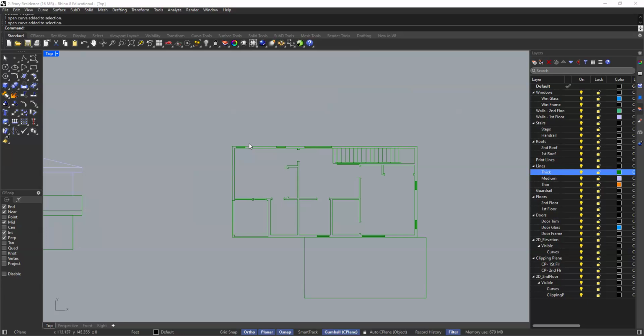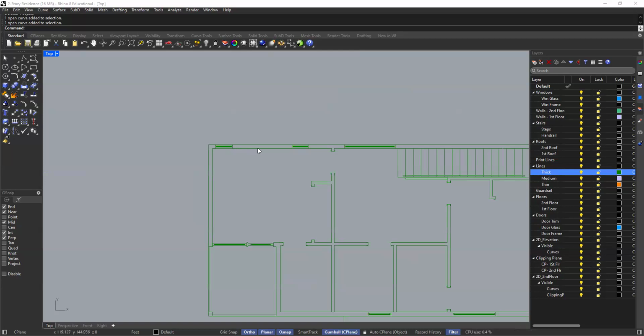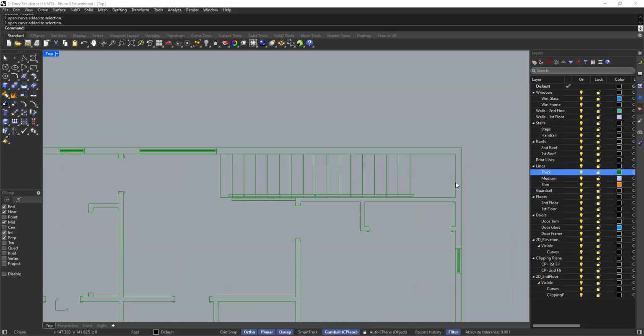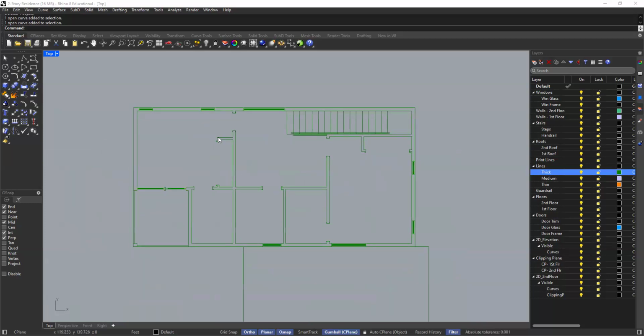Now we want to go ahead and poche. Poche refers to hatching or filling in any of the walls that are being cut through, right? The idea is that we're trying to signify a solid mass, something that we're actually cutting through versus things that are falling along in the background. We can always use line weights, a heavier or thinner line weight, to show that differentiation. But a solid poche, like filling in, is much more clear and visually much easier on the eyes to really see what's solid, what we're cutting through versus what we're not cutting through.